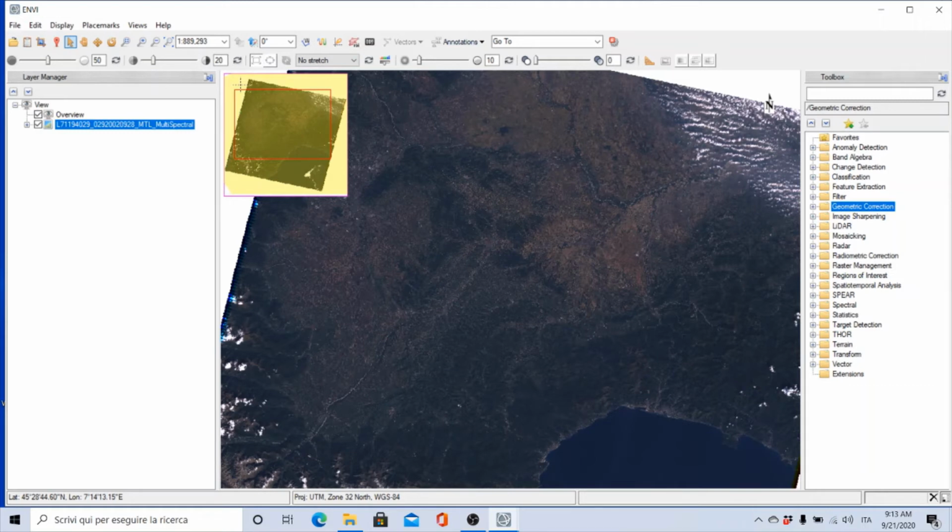This image is georeferenced, and in order to reproject this image in a particular geographic reference system, due to the fact that the orbit of the satellite that is carrying the sensor is inclined with respect to the plane that is crossing the north and south poles, the acquisition is inclined. So when you are reprojecting the data, the image is rotated.